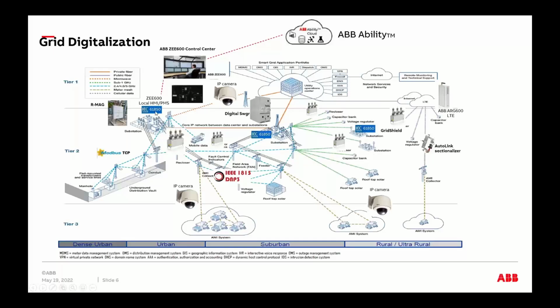So you could see here, I'm showing you 3 main protocols: 61850 in the substation, DNP3 outside the fence, Modbus TCP, for example, and so on. So all these communication protocols have a limitation depending on the data you're pulling. So I hope this is the bigger picture that you're seeing. It is more than just putting digital products or digital devices, and then the puzzle is how to make them work together to fulfill that specific application that you're trying to achieve. It could be a spec, or you could be acting as a consultant to whoever is your customer or the end user.